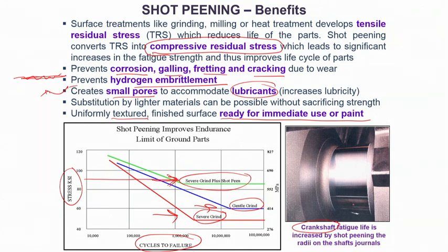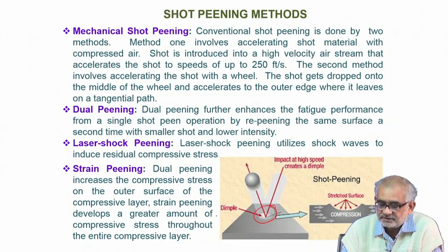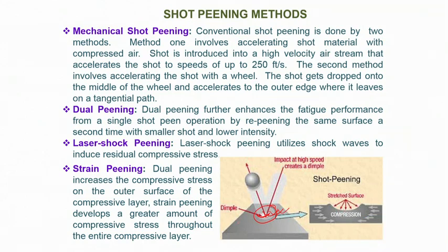Now, because of the large size, you cannot do operations easily on this kind of component, but you can bring in a gun and do shot peening on this curved surface, and create residual compressive stress, and that's how you can improve the fatigue strength. I have already explained that when the impact happens, you create a small indentation or so-called dimple, and there is a little curvature created. Due to multiple subsequent shots from several other randomly falling objects, this will essentially create a uniform depth of deformation and uniform area coverage throughout the surface.